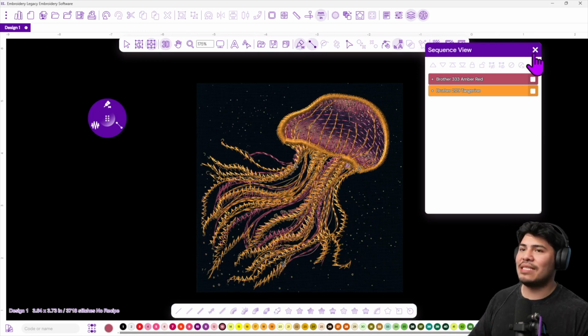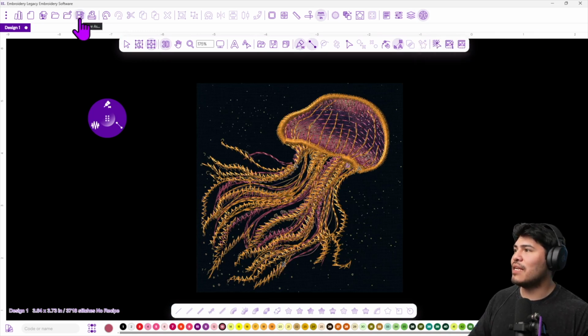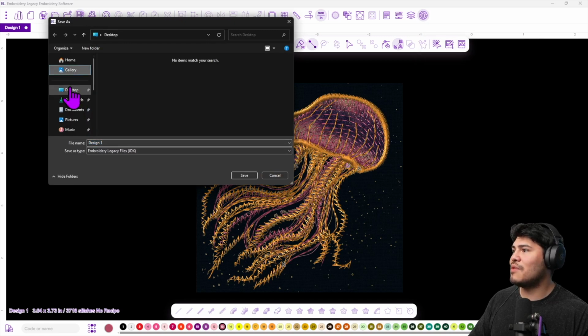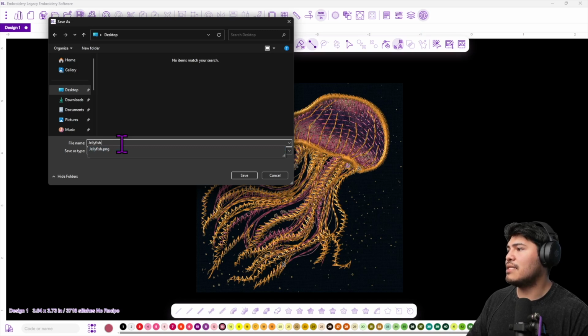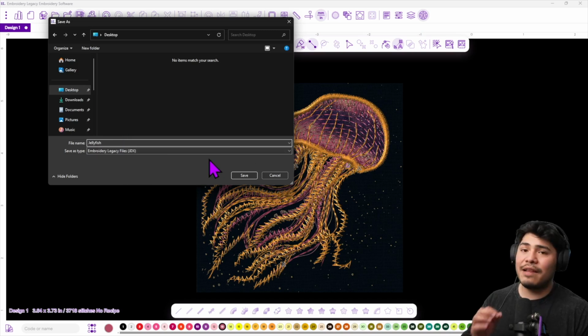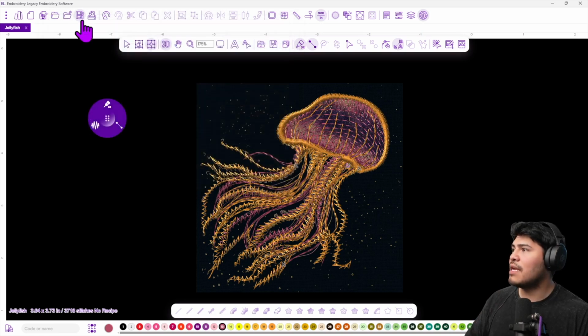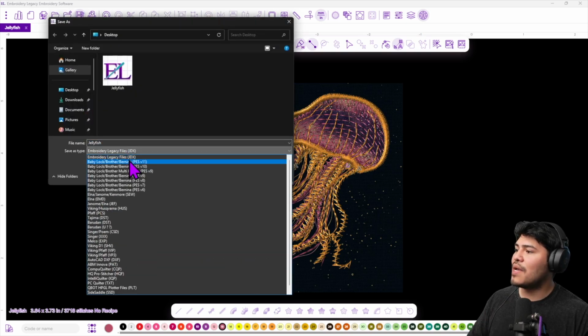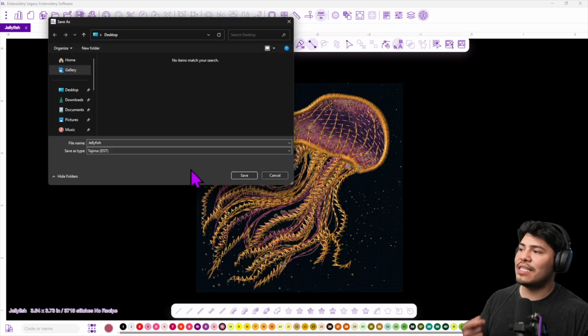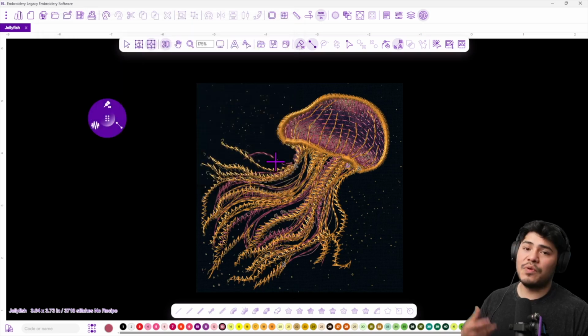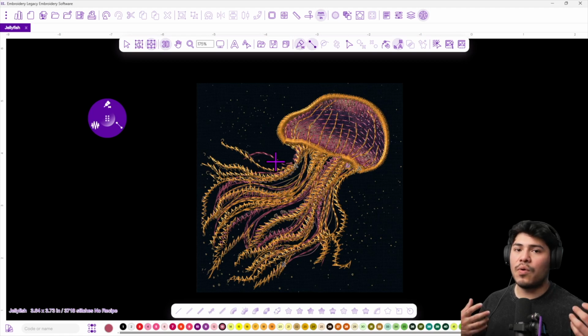Last thing to do is to save this design. I'm going to click on Save As, and I'm going to save this, very important, JDX, so Jellyfish. Okay, save it as a JDX because that is your native file format that is going to allow you to go back and edit this design in the future. So save, and now I'm going to click Save As one more time, and I'm going to save it as a Tajima DST because that's what we run here. So save it as a DST. You would save it as a Brother PES or JEF depending on the machine file format that you have.